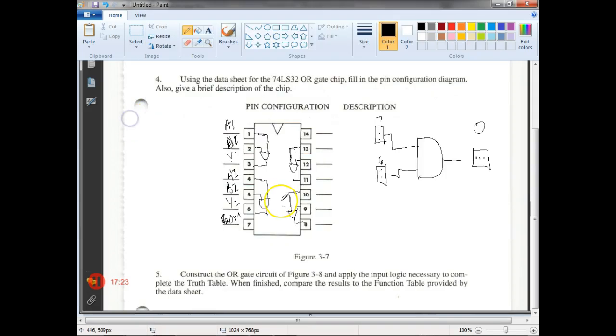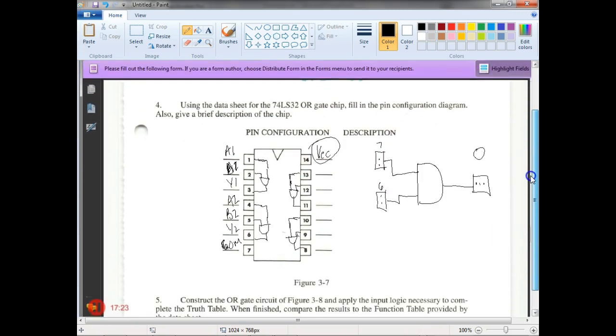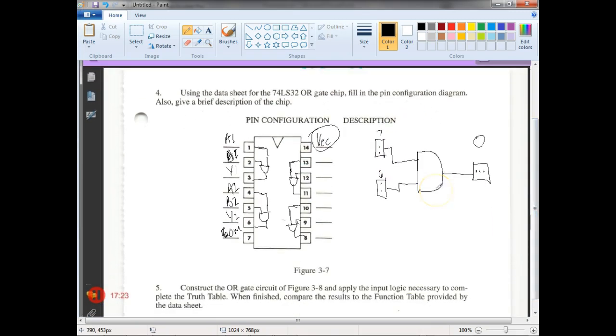Right? That makes sense? Now, one thing people forget to do is forget to do what? They forget to power it up. Yeah, they'll come up here and look at this diagram right here, and these diagrams don't show the power, they just show you how, right? You understand that? But it's up to you to understand that these guys don't work unless you hook up the VCC and the common, right? Everybody understand that? Somebody in this class is going to do that. They're going to wire it up. This thing's not working.